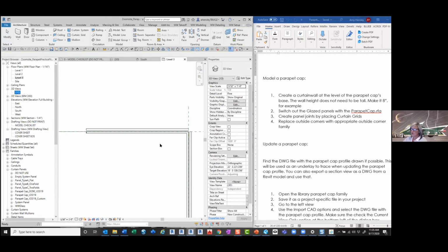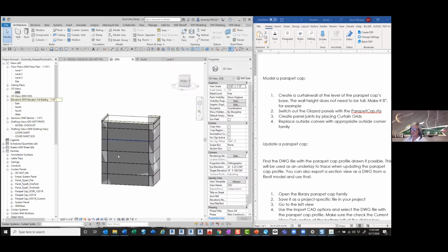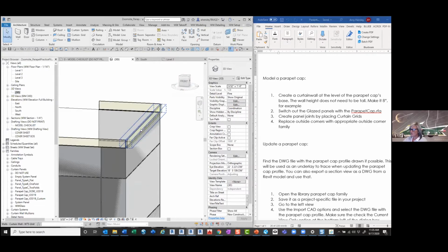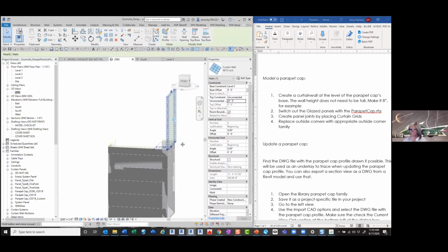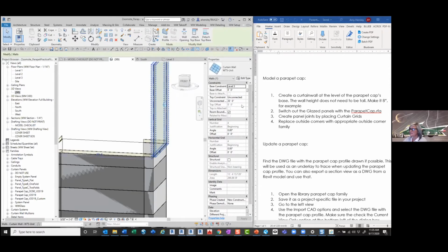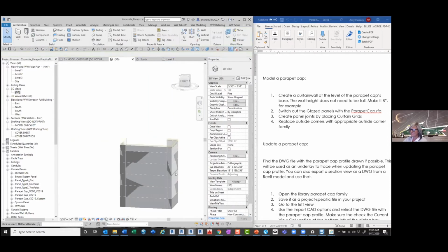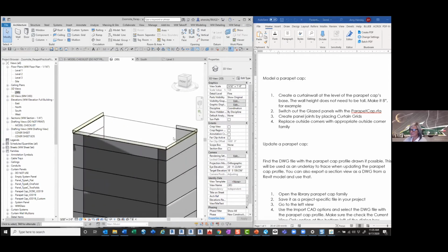If we go to the 3D view, double click on that 3D view, and you'll see our little short walls. If we had started and not set that, you might have a wall that looks like this, 20 feet, right? So if you did do that, because I forgot to mention it, and yours is, oh, it should be set. Actually, I think it's preset in this file anyway. Just go ahead and set that to like 8 inches. So you should have something that looks like this.